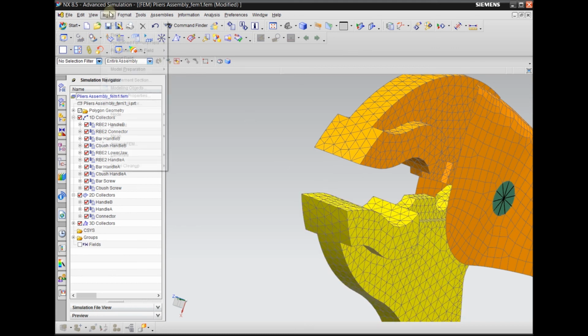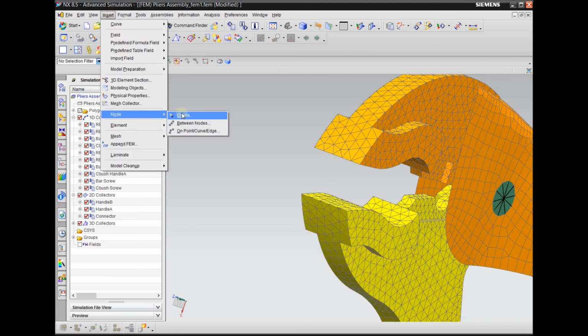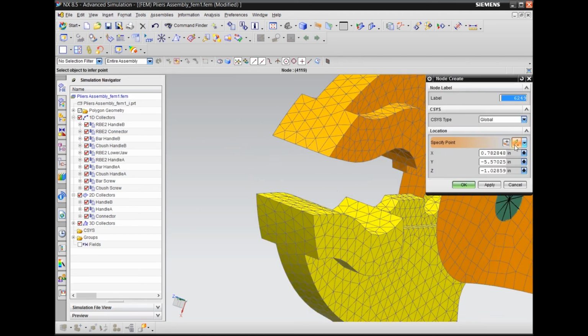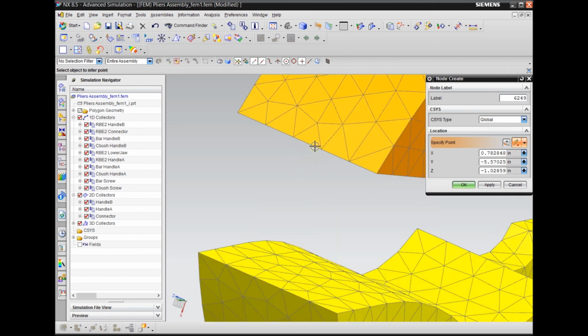If you create it that way, the piece will be welded to the jaw. So we need 4 nodes first. We need to create nodes. Okay, and make sure it's on invert, and we can pick the center 2 nodes and create 2 nodes on top of them, 1, apply.